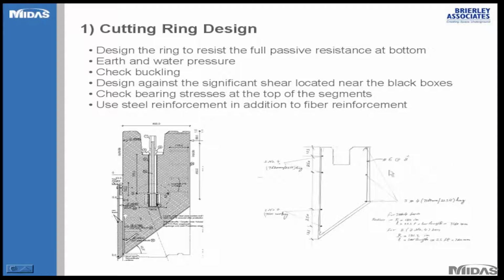As you see here, you don't have very heavy reinforcement. All you see is number 6 longitudinal bars, or actually ties, and some circumferential reinforcement like number 4. So it's not really a very heavy reinforcement. Again, that's because you take into consideration the soil structure interaction, so you don't have to use very heavy reinforcement here. And that's actually the main point of discussing this, that you don't need too much reinforcement.